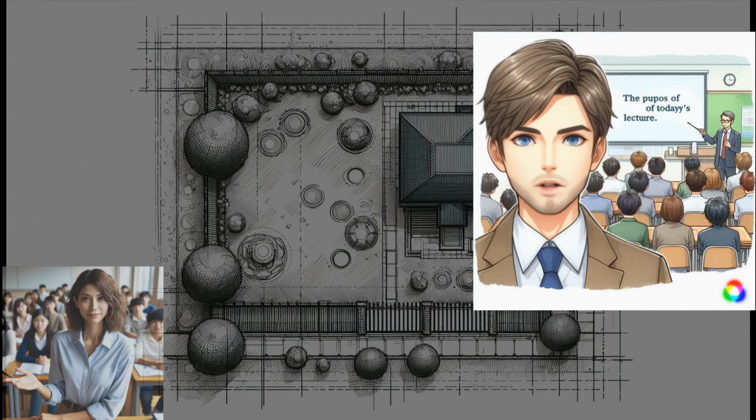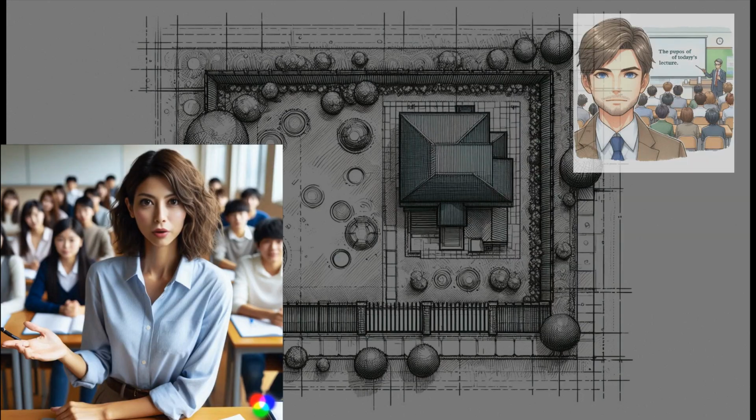We shall see in this video how to overlay an image in the background in AutoCAD and draw entities over it. Certainly, we already have a top view image of a plot. We will use it and draw boundary, trees, etc. Henceforth, we shall be using this image.